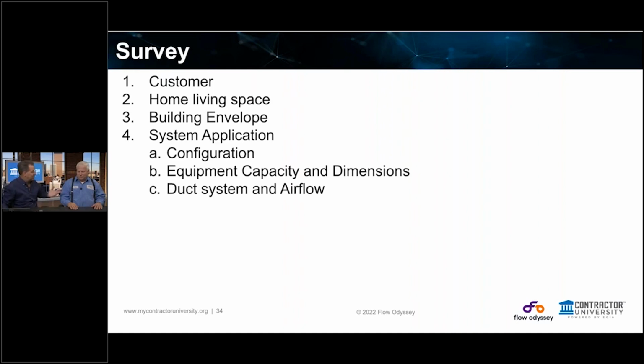We're going to look at the duct system and the airflows we talked about yesterday, right? And gather the information, all that. You've got to crawl the entire duct system. See where it all is connected, see how it's installed, look for broken ducts, disconnected ducts. Again, a lot of the stuff you'll see in the survey packet as to where to look for these problems. You're looking for dampers, looking for the different types of supply registers. Do they have the right registers on there? Air conditioning registers versus heating registers. Leaky ductwork,